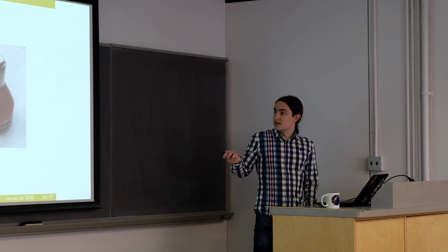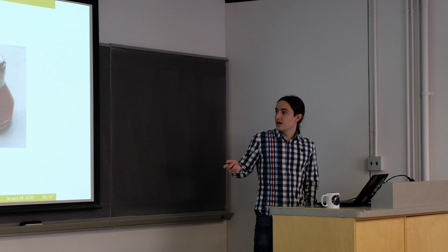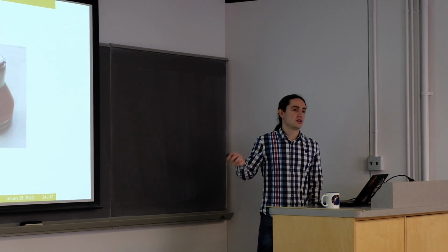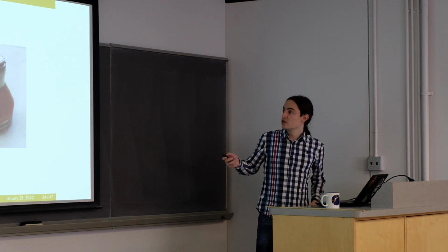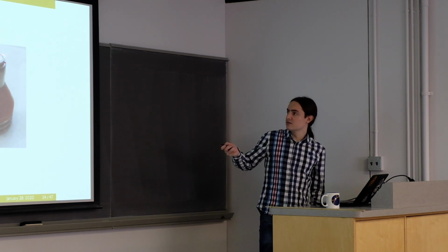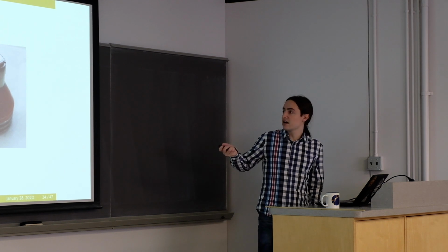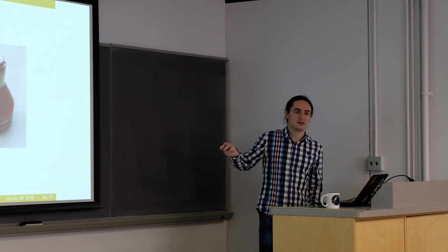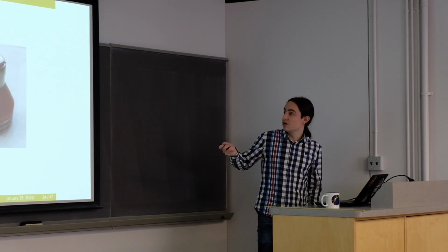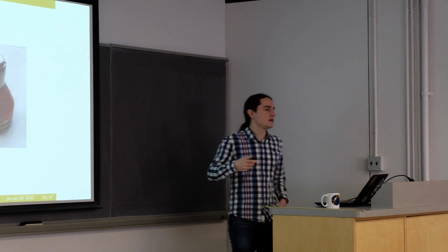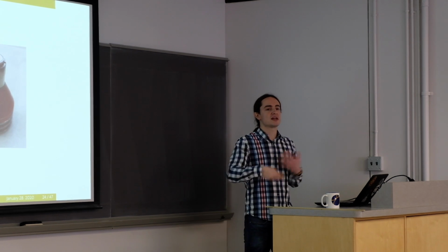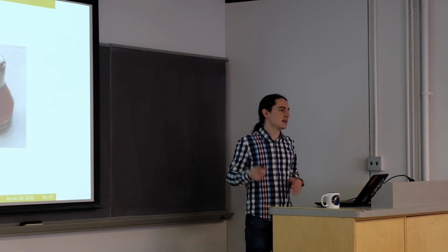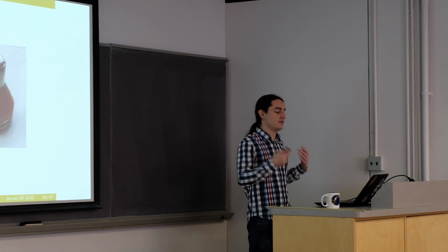So what we did is this redesign, where we cut the upper layer and make these slits, so we can introduce the copper target inside. See here, an unused target, where the huge part that is sputtered is concentrated in the material, but also this halo of places where there was not so much sputtering is also in the copper. So we know that everything coming from the target is coming from the copper.